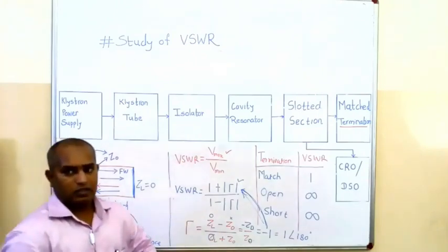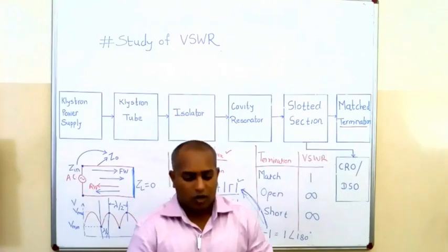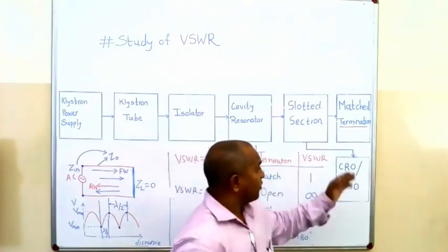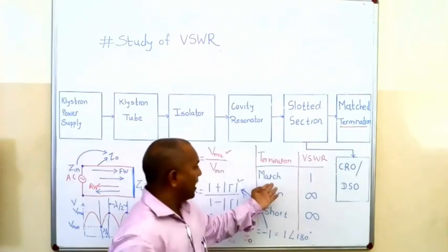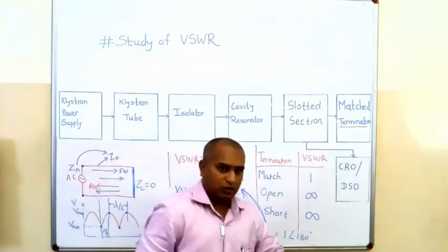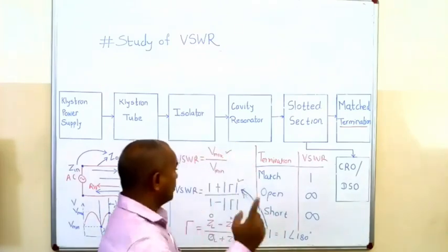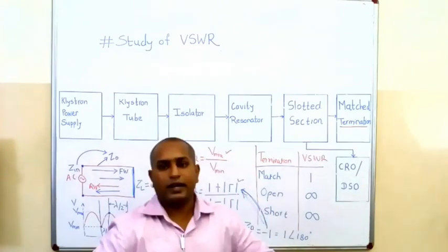So in this way, we will measure the VSWR with respect to the different terminations like match, open and short. And we will check our reading of VSWR with the ideal condition.